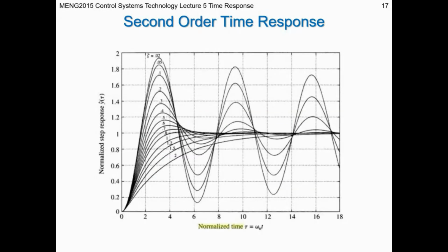And we can expand this. What we have here is the same system plotted with just different zetas. Running through from zeta being very low indeed, which is 0.2 here, and as you go in this direction, your zeta is increasing. This is 0.5 zeta. So it gives you the form of the response for different zetas, and then it goes above 1. You can see that the highest value is zeta equals 2, and this is just the overdamped, sluggish response.